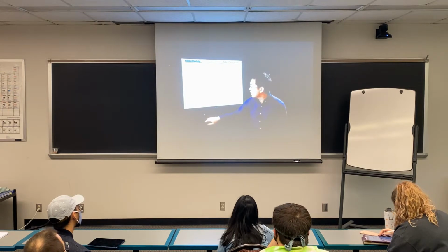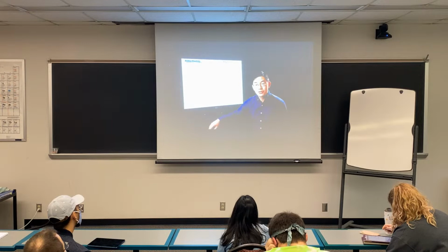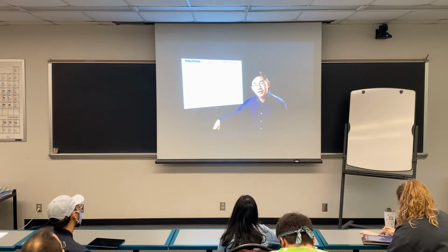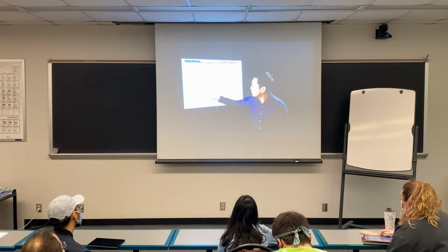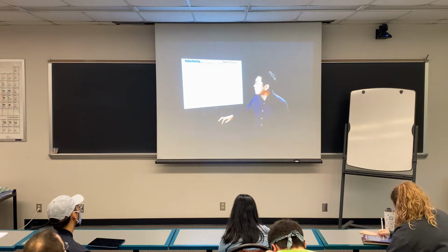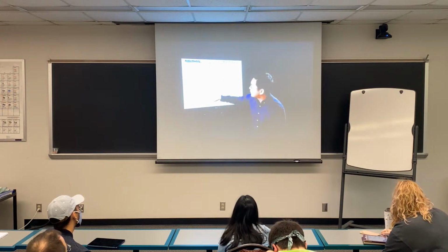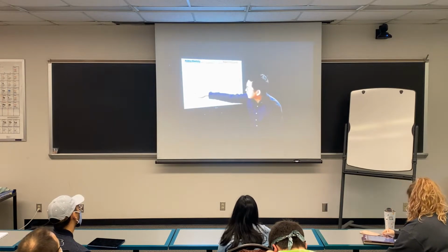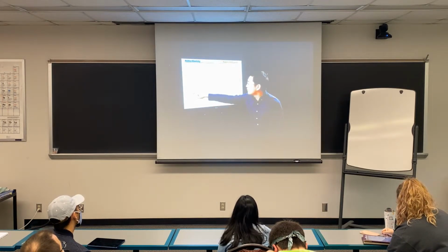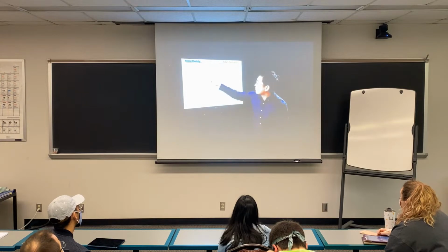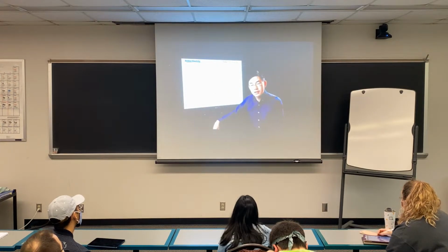But once your strain is above 5, your rubber elasticity deviates dramatically from the theory, and this is what you see. It can be up to 100% difference: the theory predicts the force per unit area will be about 3.0, while the reality, if you measure it, already exceeds 6. That's a big difference.